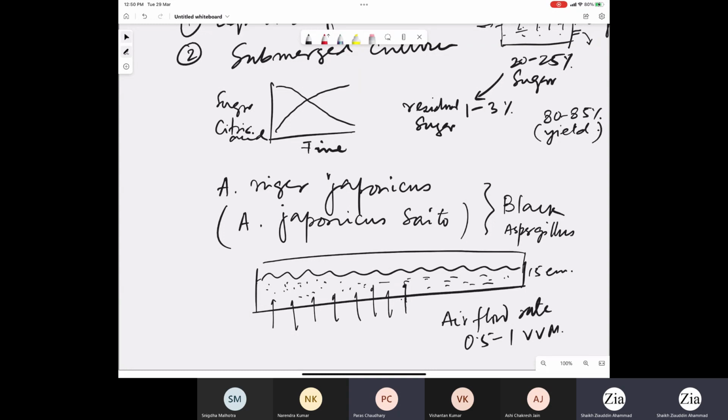You can add ferrocyanide in a stepwise manner by watching the precipitation. First you start with a low amount like 20 ppm, and then slowly increase it to 80, 100 ppm for the initial growth phase. Obviously, when growth increases, you need to make sure the grown culture does not interact with the ions, so you have to use more ferrocyanide to remove the iron from the system.